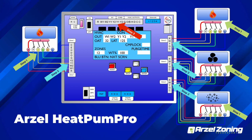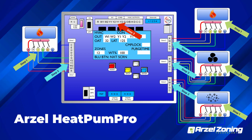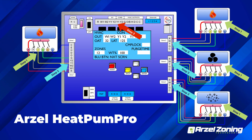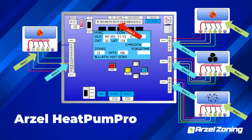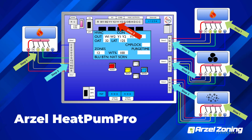So rather than turning a thermostat on, saying the equipment's not working, and then instantly condemning the Arzel board, we need to take a look and verify that the thermostat's doing what it says it's doing, and then see what the panel says it's doing and verify that as well.